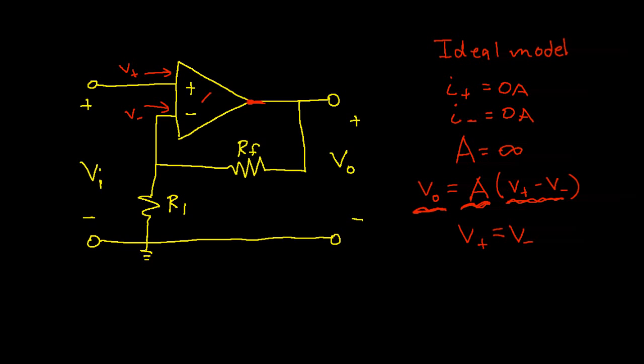If you'll remember, hidden away inside this op-amp is a controlled voltage source, and this typically goes down to ground. And so basically what happens is the op-amp sets the output of this voltage source to be whatever it needs to be in order to make these two inputs equal. Now in real life this is constrained by the fact that real op-amps aren't just ideal voltage sources. They have limits in terms of how much current they can supply. They have limits in terms of maximum and minimum voltages. But again, for the ideal model, we'll think of it this way.